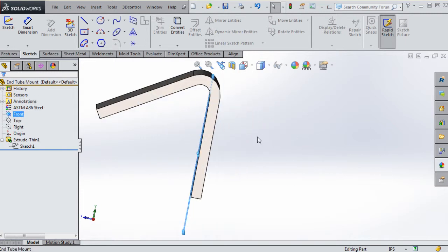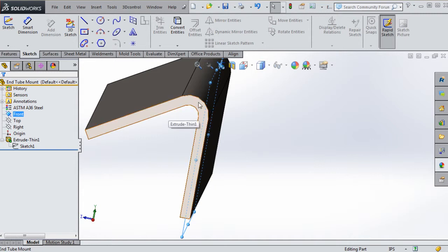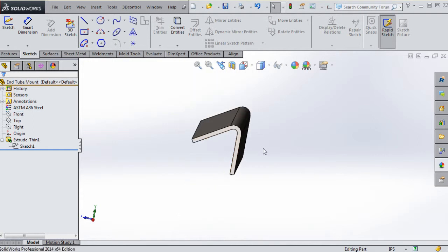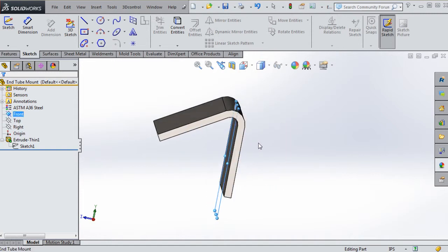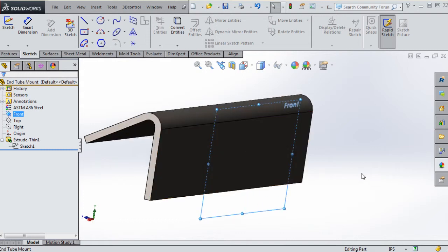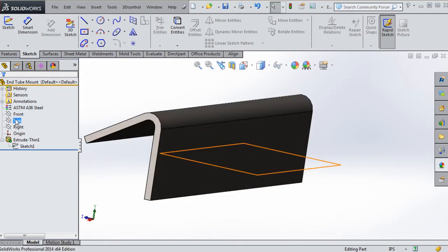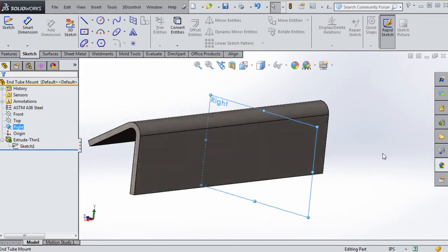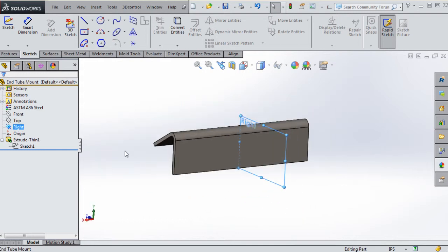The reason I didn't do that this time was I didn't really want to resolve the issue of some of the angles in here and the fillets. I knew I wanted a 1/4 inch fillet in here, and it resolves out to a 1/2 inch on the outside. But we don't really necessarily need to put the front plane right in the middle of the model here. In fact, we can't do it and maintain the symmetry, but we do have that model geometry available with the top plane and the right plane. Now it'll become apparent once we put our model together and put that into our assembly.